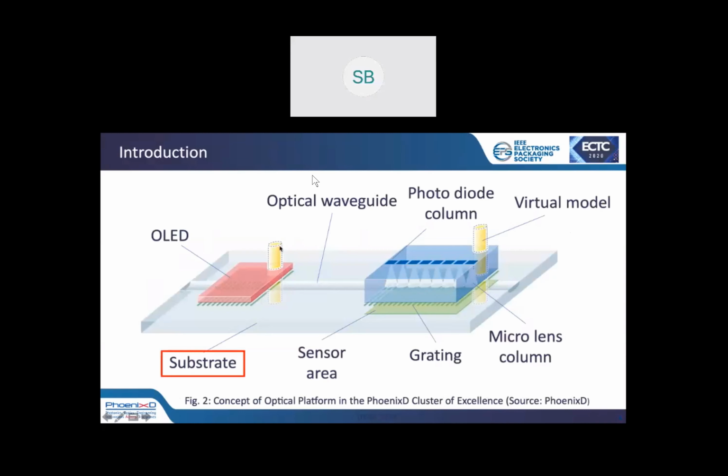An interesting question in this case is we use a composite polymer material regarding the laser direct structurable PEEK. This material has particles inside its polymer matrix for the laser direct structuring. These particles are in between 1 to 5 micrometers diameter, therefore creating a surface with a high surface quality of roughnesses below 30 nanometers for optical purposes is hard to achieve.